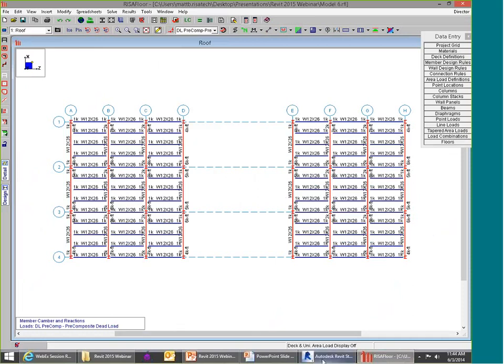And so you can see by using that horizontal bracing trick, you can bring all sorts of members, at least beam-type members, from Revit into RISA Floor and get around some of the geometry restrictions in RISA Floor that wouldn't allow things like curved bridges, and just get your analysis all in one model. So another handy tool to have available.